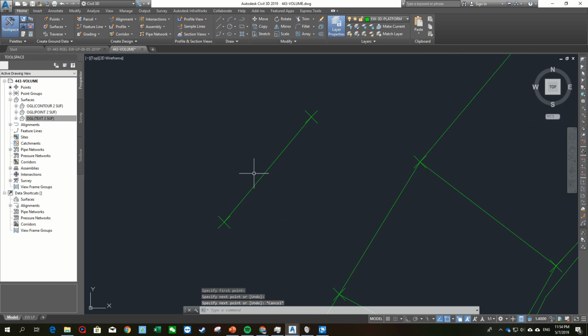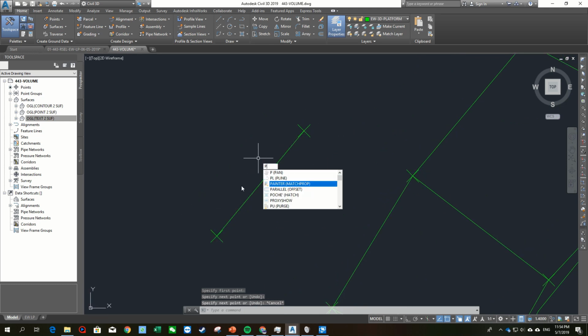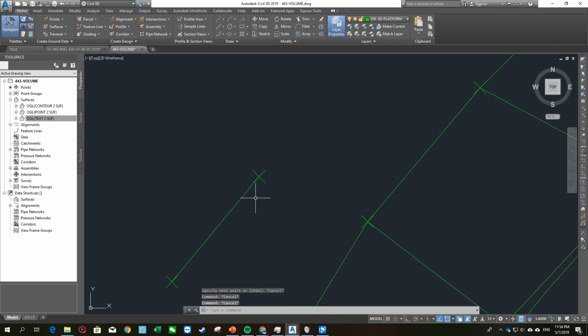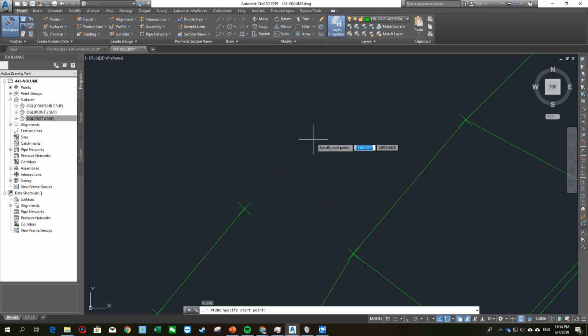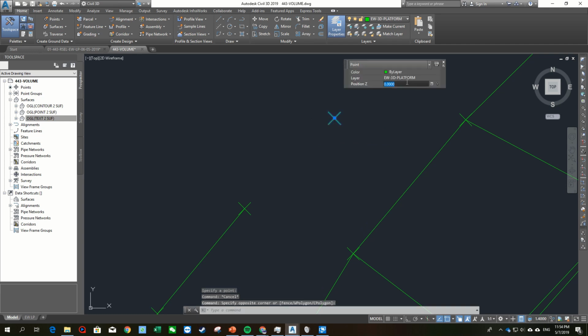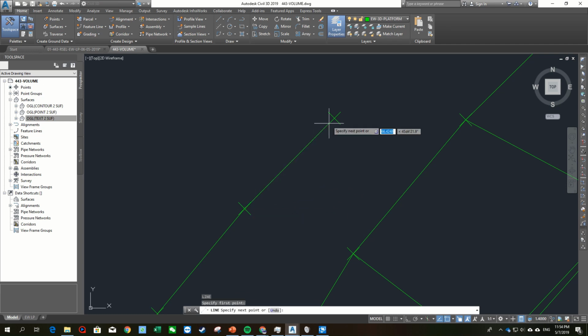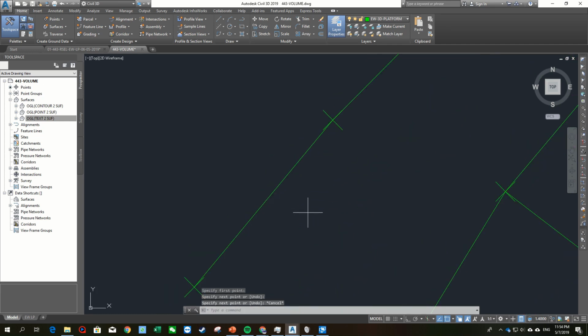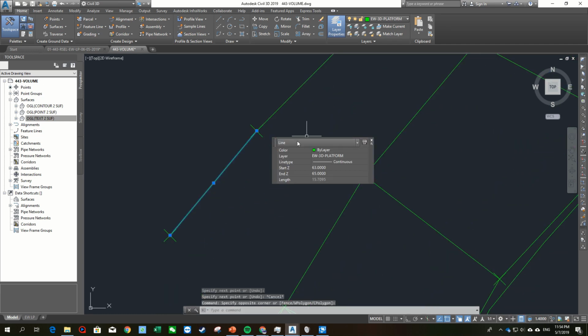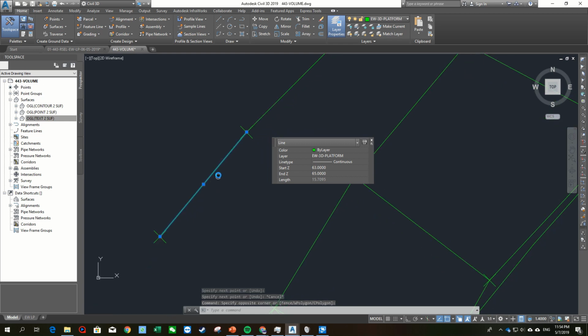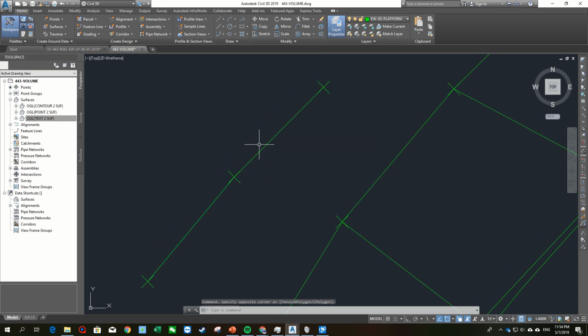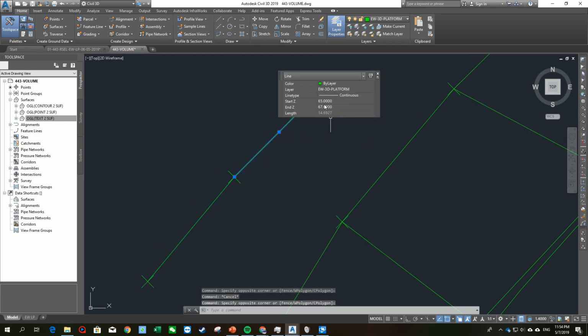For the middle one, actually you can interpolate that, or you don't have to do that also, never mind. Or if you have another level, you can use the point, create another. Let's say this one is 67. So you click line to do that. I prefer to use lines instead of polyline for this, because it has two different z values, 65, 63, and this line 65, 67.